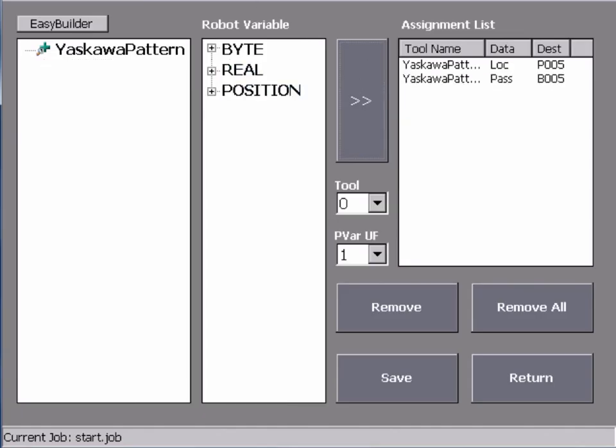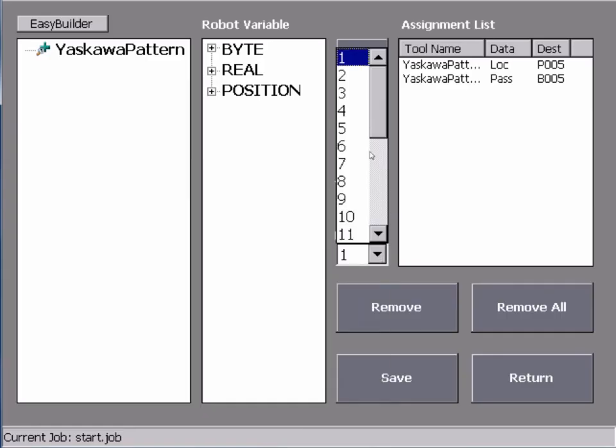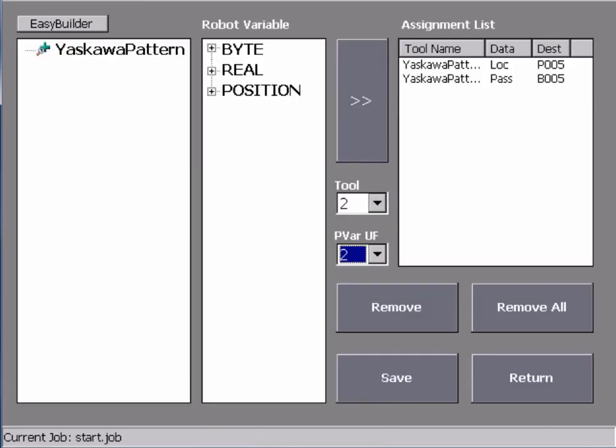B5. It's important to note the user frame number box and camera TCP number box. If you have a fixed camera, the number in the user frame box is the only thing you need. However, if you have a mobile camera, the camera TCP is the most important argument, and it's recommended to set the user frame box to the number of the user frame we created for the grid calibration. If an undefined user frame number is selected, the P variable that uses it becomes invalid.